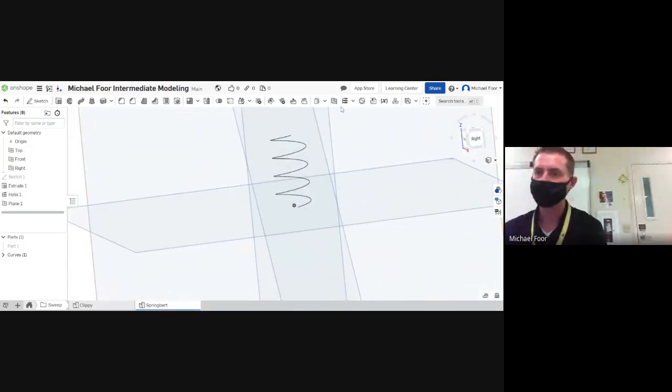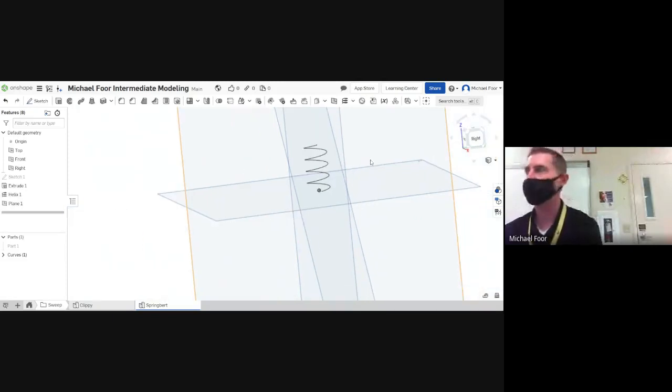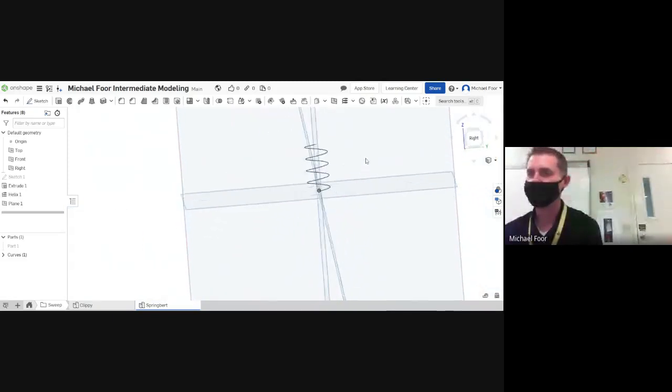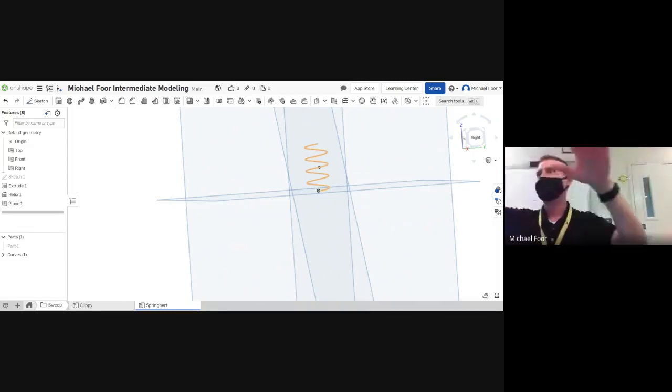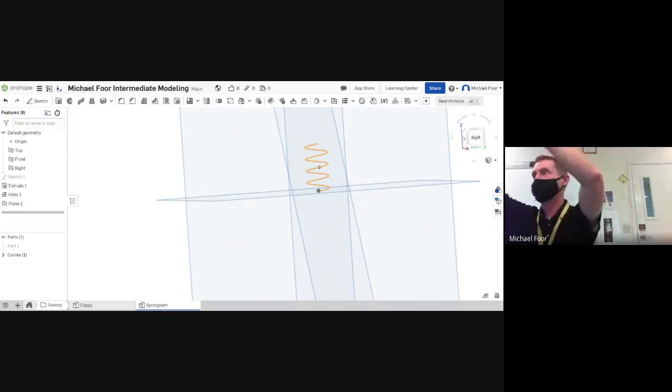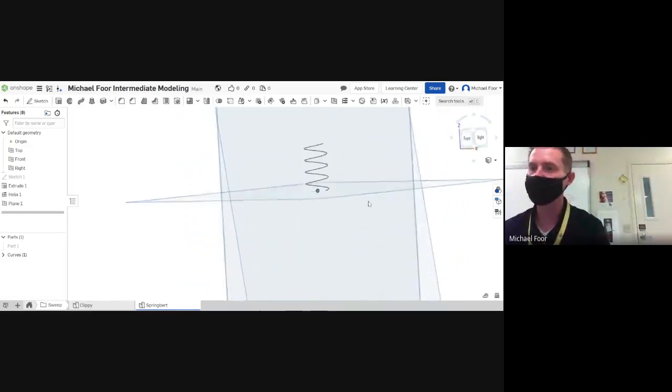So these work planes, this function right here lets us draw planes to do a whole lot of different stuff. This one created a point right there. If you had your paperclip drawn and you didn't start on the origin, you could have created a point on the edge by doing just this right here. If you had created your paperclip way off to the side and the origin was right there and you couldn't draw on that, you could have created a plane right there to sketch on. So planes are actually pretty useful. All right, so go ahead and peek my screen.